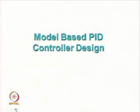Welcome to the lecture titled Model Based PID Controller Design. Controllers designed based on phase and gain margins are found to be satisfactory. An attempt will be made in this lecture to design simple PID controllers based on phase and gain margins. The phase and gain margins are user defined, therefore, one has to choose the phase and gain margins judiciously to design proper PID controllers.